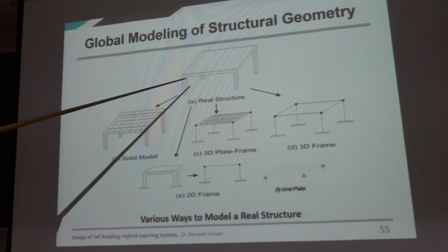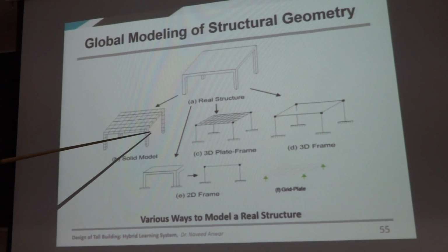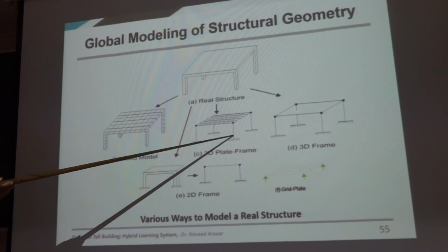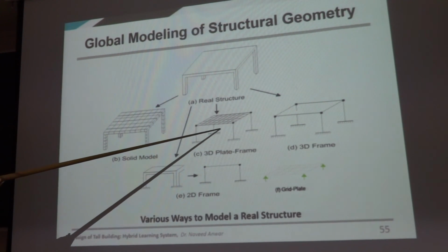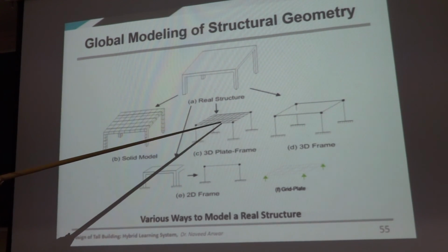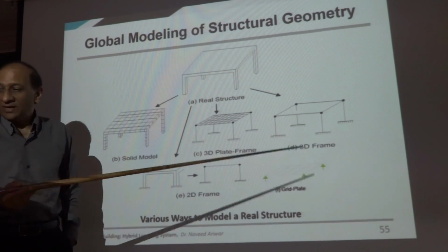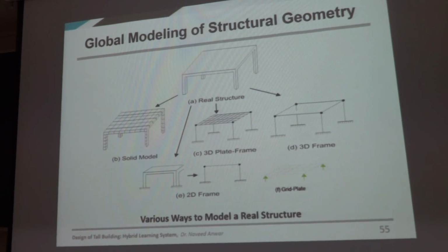So we could model this by using solid elements, 3D elements, dividing everything properly with everything in detail, or I can model the columns by 1D elements and the top as a 2D element, or I can convert that into an equivalent beam. I can say part of this is like a beam, with 4 beams with so much thickness, right?